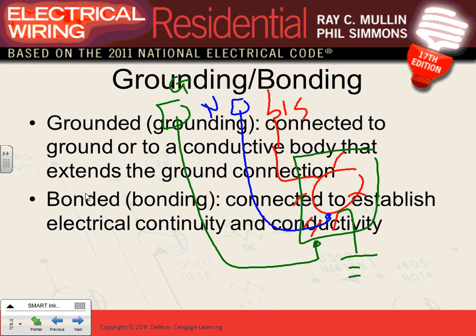If the frame is not grounded to the ground slot, the voltage will be sitting there for you to grab the handle of the fridge and it goes right through you, especially if you're barefoot in the basement where your beer is, and burns you, basically. So that's where we got the ground. Now, if it's grounded, you're going to have a short circuit, what they call a ground fault, hot to the ground, and that will facilitate the operation of Mr. Protector here, called the circuit breaker, and it will trip the circuit breaker almost instantly.